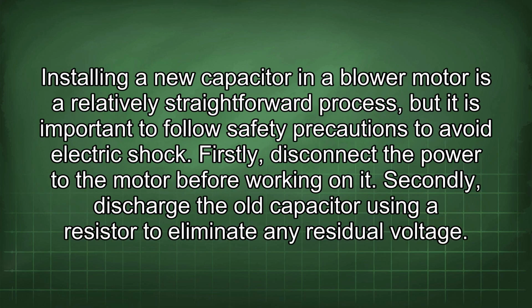Installing a new capacitor in a blower motor is a relatively straightforward process, but it is important to follow safety precautions to avoid electric shock. Firstly, disconnect the power to the motor before working on it.